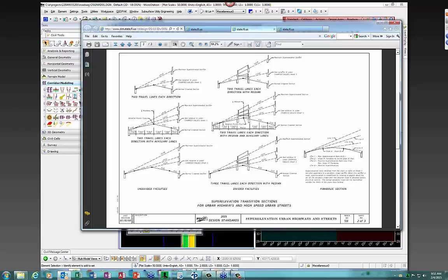Okay? So all you would do is you would come into your, unfortunately this is left is our project that should rotate about the right side, but let's just assume it's that way in this diagram. So I would have set up my lane 1 as left 28 feet, lane 2 would be left at 11 feet, lane 3 would be at plus 2%, and then lane 3 would be again left, and it would start at 39 or whatever that total width was for 11 feet, but it would be a negative 2, and then so on and so forth.